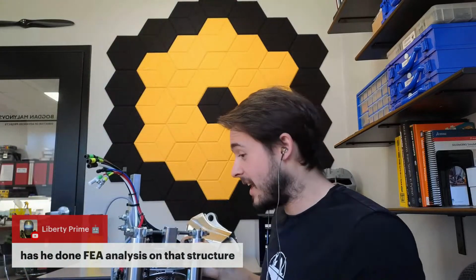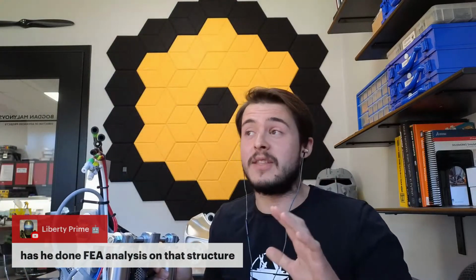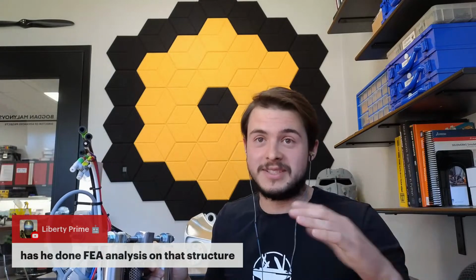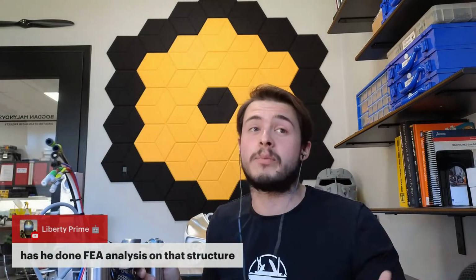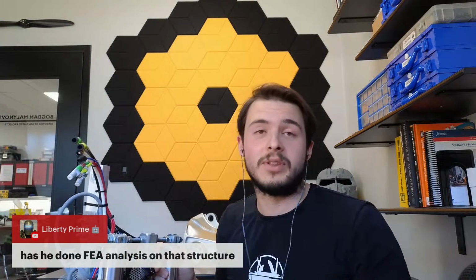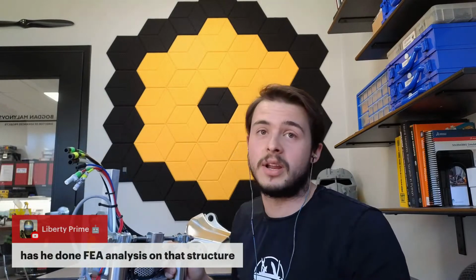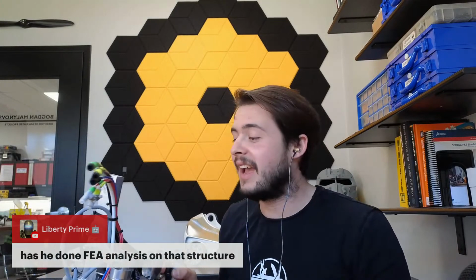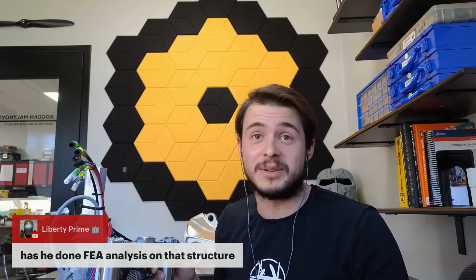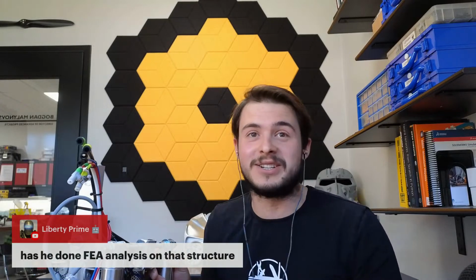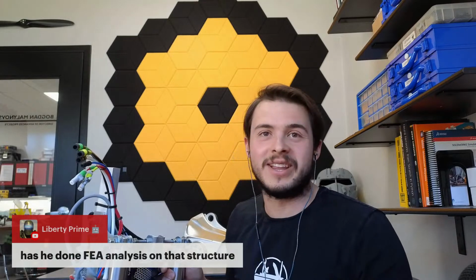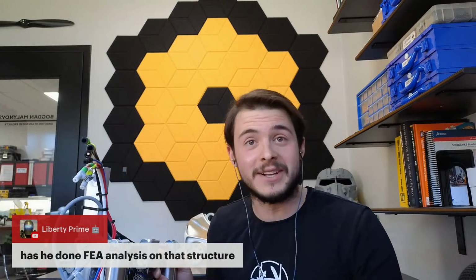The legs, I believe James ran FE analysis on them about 8 years ago. The ones that you see in the body right now, we're going to be modifying them and improving them. But absolutely, all of our parts that are going to be under loading are going to be run through FE analysis, and make sure that they're not going to harm the user. Because if you're picking up a car, if you've got 2,000 pounds of weight on your legs that are supported by pneumatic cylinders and that fails, you're going to have a really, really bad day.